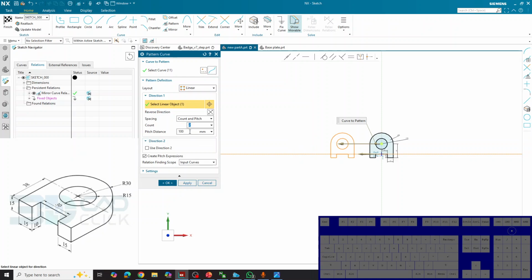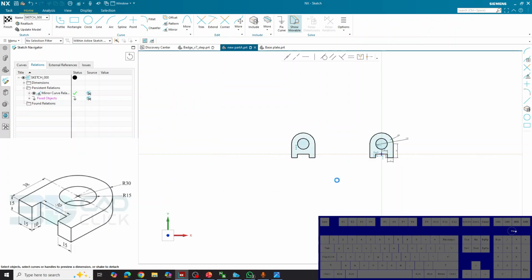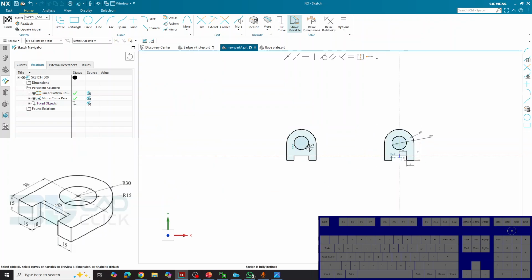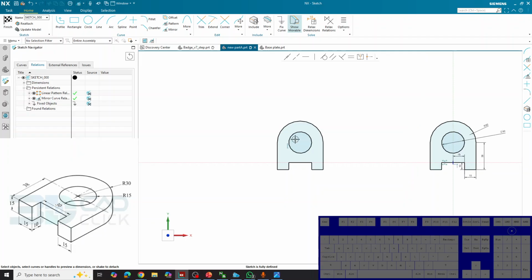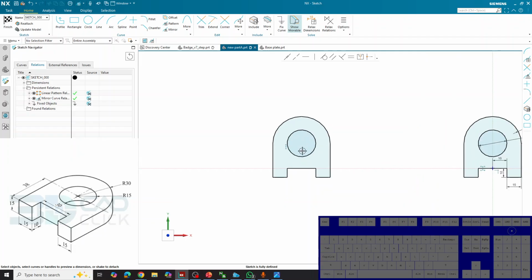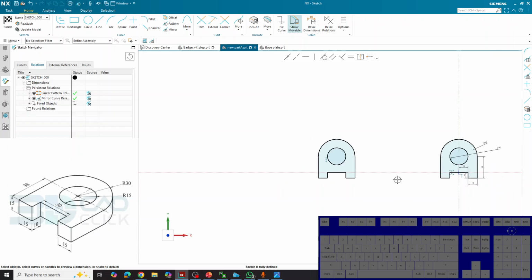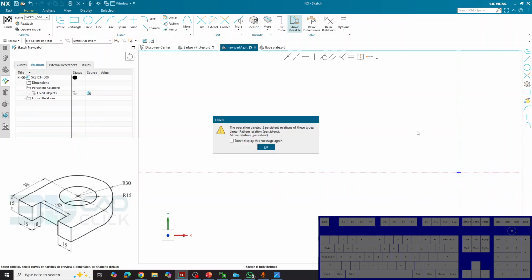Let's increase this a little bit more, just because I want to just mess around with this duplicate. Okay. So ignore this for now. Okay. This is what we will keep and treasure. Okay. We're going to focus on this sketch now. And notice that even though it is not dimensioned, it's still colored in black because it knows that it's referencing this sketch over here. If you were to delete this by accident, this would lose the reference and therefore this would also disappear. Okay.